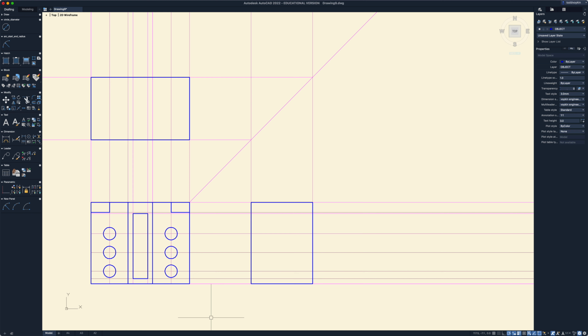There's our front view. Now I need to go back into my offset and create a couple more of the offsets for these two lines right here, which is offset at 10. So I'm just going to go offset 10, you're going to go up, and you're going to go down. And again, I'll go back into my line command in the object layer, and I will begin to draw this object like so.